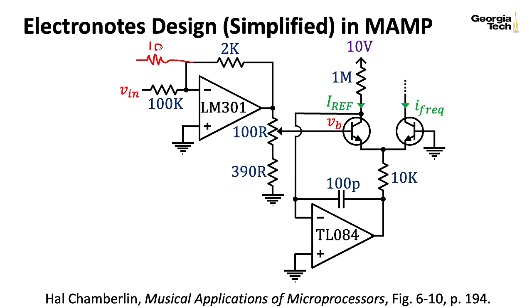And quite often you would put a few other things in here. You might put a potentiometer in front of one of these, and then you would have another input here. This might be a low frequency oscillator to make either a siren kind of sound or a more subtle vibrato sound like a violin player or an opera singer might use. And you would use this pot to control how much that LFO influences the pitch.